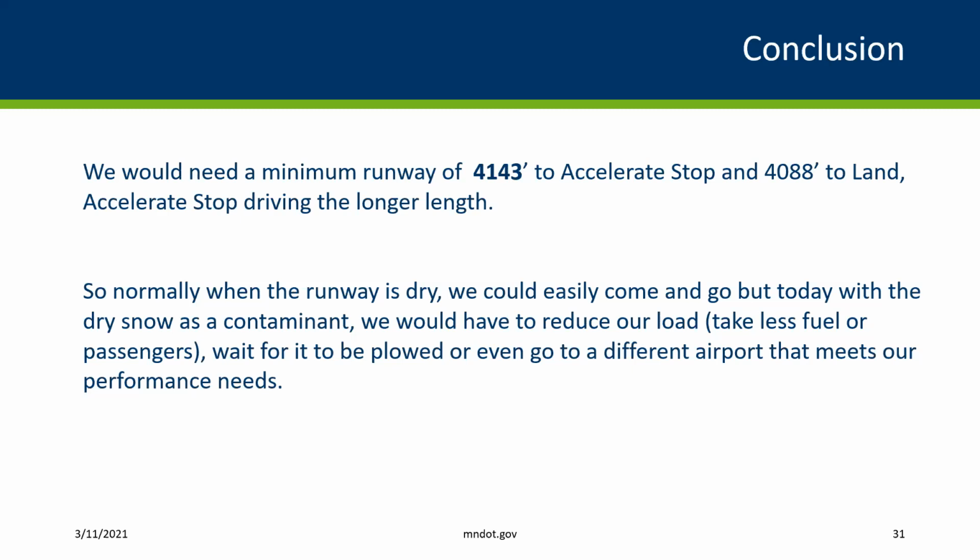But today we would either reduce our fuel load or passenger load to get our weight category down so we can make it better, or we wait for it to be plowed. Or the last option would be to go to a different airport that meets our performance needs that day. So even though we could come in normally in dry conditions, by you issuing that and giving us that information, we're able to safely plan that trip and follow the FAA's best guidance.